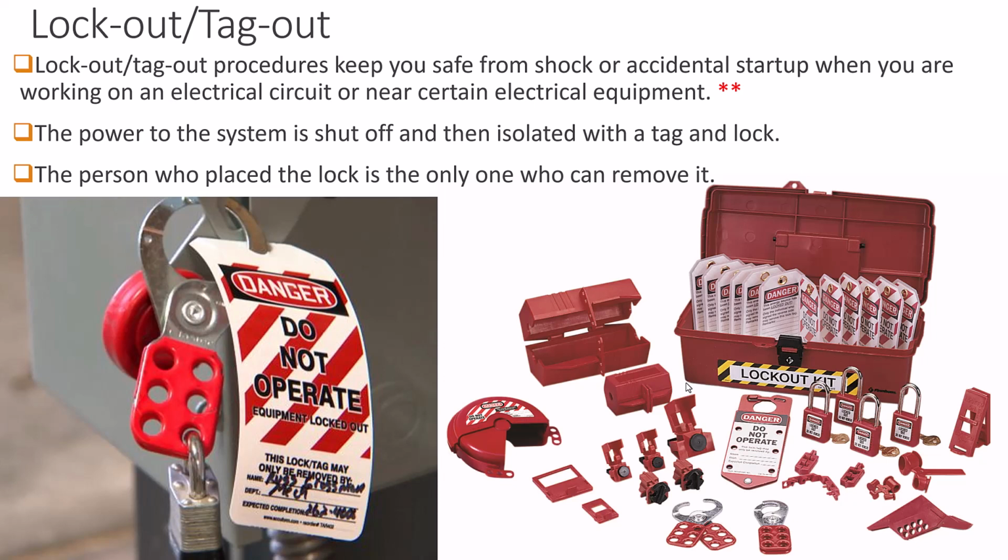So that shroud that you see at the very left-hand side, the furthest thing in that picture, is meant to go around a handle of a valve. And so in a lockout tagout process, the person who puts the lock on the device is the only one that should be removing it. And they keep the key, and they shouldn't be using combination locks.